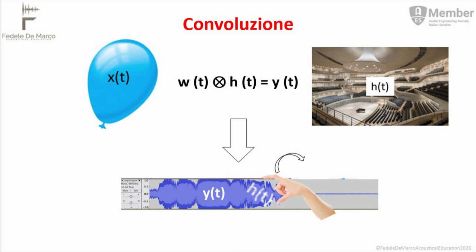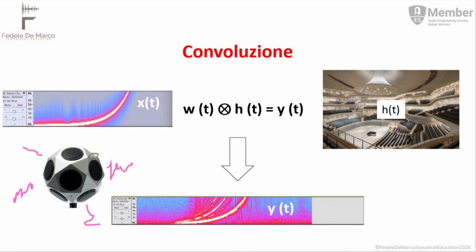The room filters any input signal with its unique fingerprint, known as the room impulse response. Think of the signal and the RIR as wave and TXT files. The process can be explained with a time domain convolution or a sum of products between their samples. I have detailed this process with Excel in the convolution videos on my YouTube channel. The IR is hidden within the output signal, and we must extract it. The recorded output signal, y(t), also contains noise and distortion products, appearing here as harmonics of the fundamental. To extract a noiseless RIR, we must simultaneously remove these artifacts.